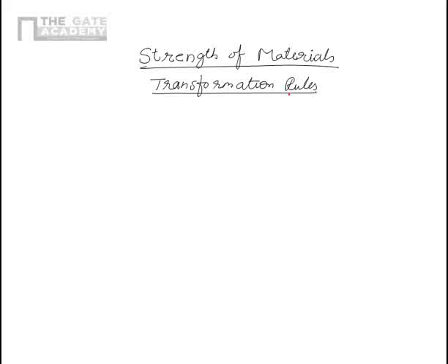So the stress element looks like this. It's a two-dimensional element which has a length and the width, and we have stresses occurring like this as well as shear stress occurring like that. So these are normal stresses. These are called sigma xx and sigma yy. This is x, and this is the shear stress, which is given by tau yx and tau xy respectively, and this is x direction and this is y direction.